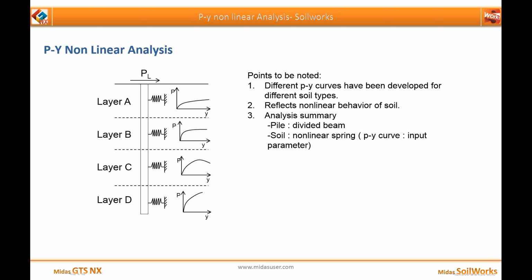Now, based on the input, if you just input those particular parameters, the PY curve will be generated for that particular soil type, which I will tell you in detail. What it does is reflect the nonlinear behavior of the soil. If we summarize, the pile is a divided beam and the soil is a nonlinear spring. The PY curve will be the input parameter which will define the